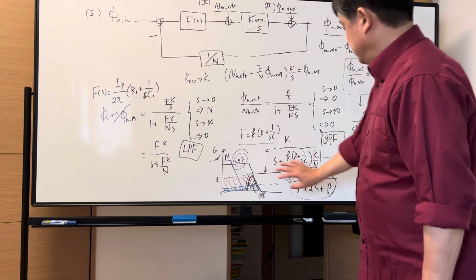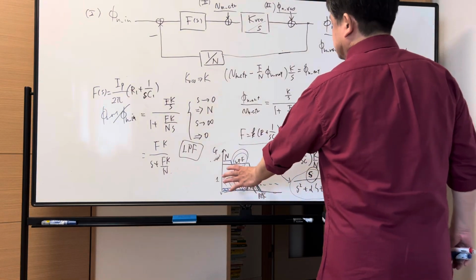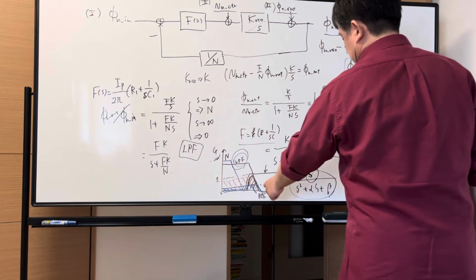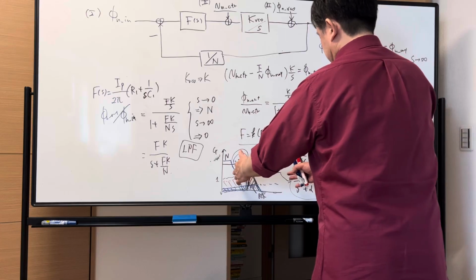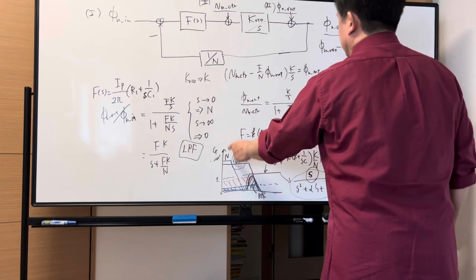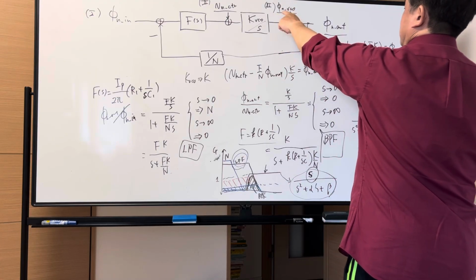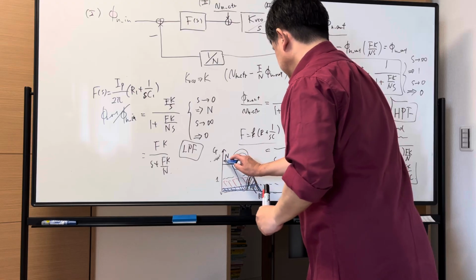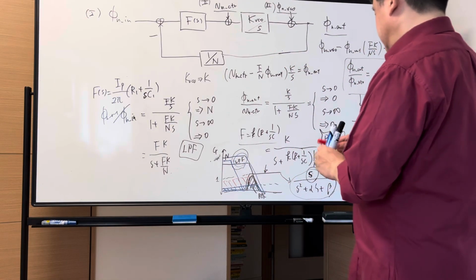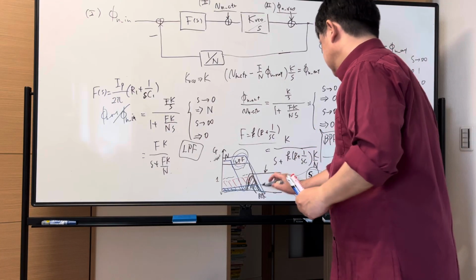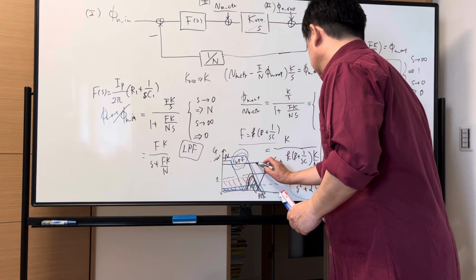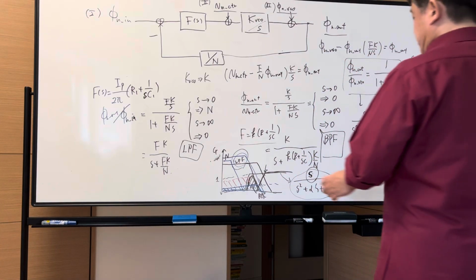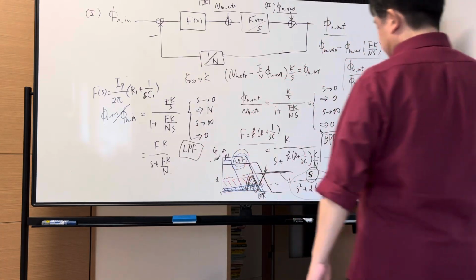So there's an optimal point for the PLL loop bandwidth. If input noise is small enough, we can make the loop bandwidth higher, and we can effectively suppress the phase noise from the VCO, even if the VCO noise is like this. We can set a higher bandwidth like this. And this is effectively suppressed with the stop band, while input phase noise couldn't be.